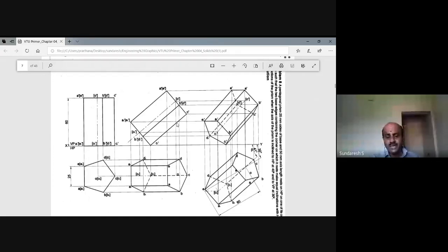Okay, if this is inclined, then of course we can show the axis also inclined to HP at 40 degrees later on. But here don't show the angle for 40 degree with respect to C dash and C1 dash. What we want to show is the axis is inclined. Okay, so once you get C1 dash and C dash, this line which is inclined 40 degrees, then you can construct the outline of the front view. So how do you do that?